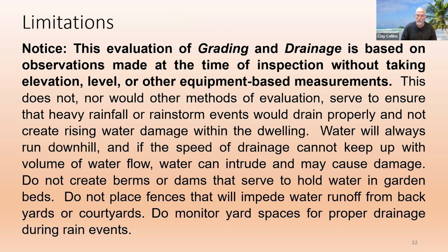So in my report, I start out the grading and drainage section like this. My evaluation is based on observations at the time of the inspection, and I'm not doing elevations. I'm not using a level, even though I have a picture later where I did, and I'm not using equipment. I'm simply standing back and taking a look at the property and trying to decide if that looks like it drains well or not. And frankly, for the most part, we can look at that and see that it will or won't. But when I'm talking to the client, I say, best I can tell, it looks like water's going to run away.